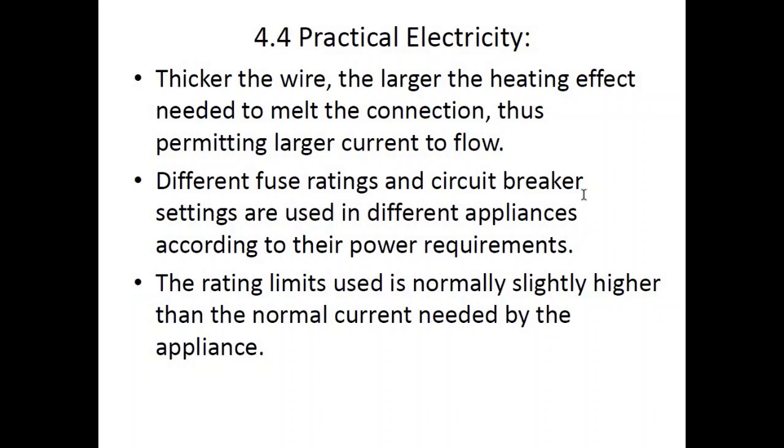Different fuse ratings and circuit breakers are used in different appliances, depending on how much power an appliance would draw. The rating limit used is normally slightly higher than the normal current needed by the appliance. What we just discussed, that it should be 10 to 20% more.